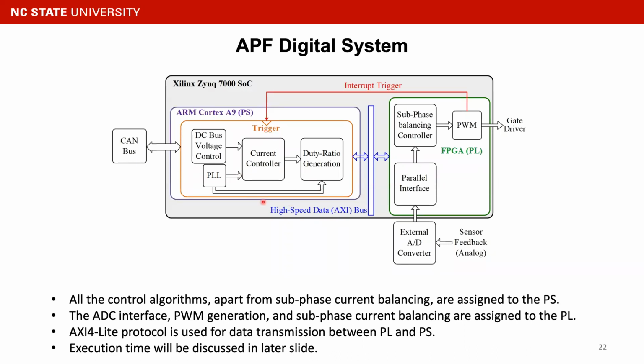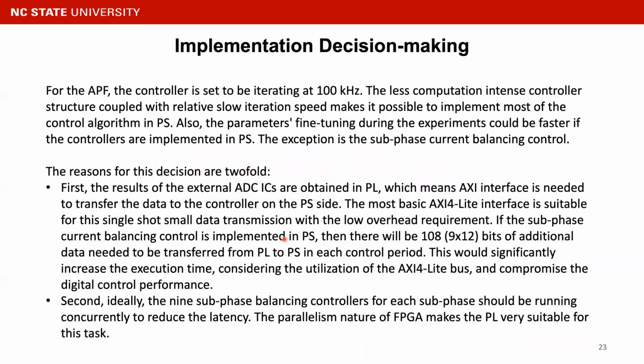While the ADC interface, PWM generation, and the subphase current balancing are assigned to the PL side. And we use the AXI4-Lite protocol for data transmission between the PL and PS. And the execution time will be discussed in later slides.